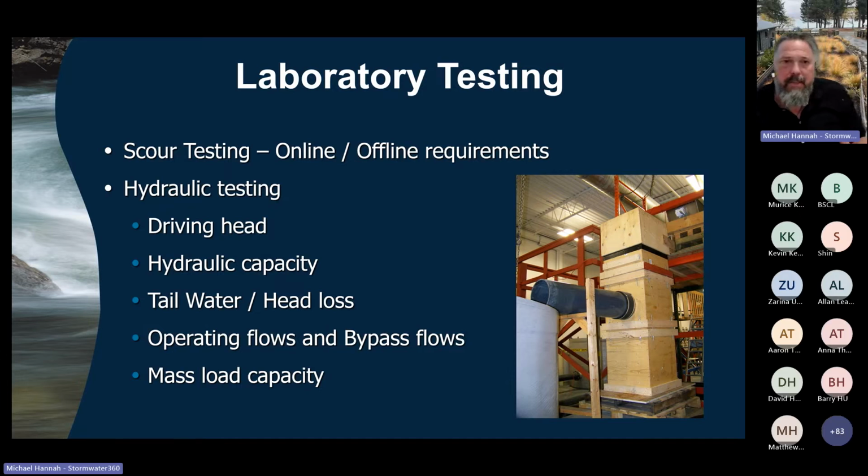It's also good for testing things that are difficult in the field, like scour testing. What happens when you get a 1 in 10 year storm? Well, you'd have to wait 10 years to capture that in the field, but you can simulate it in the lab. It's also really good for resuspension testing, which drives whether a device should be placed online or offline.